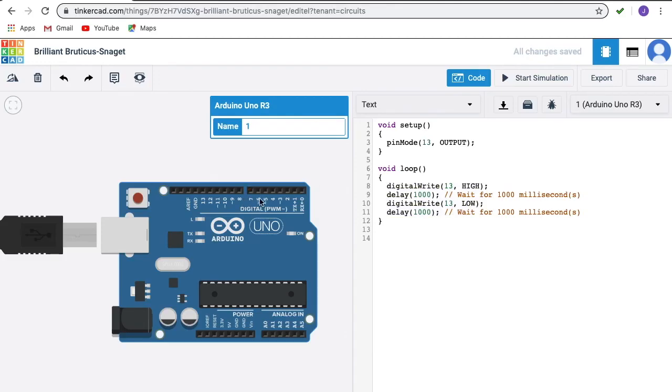This is a digital pin, either 0 or 1 is going to be here in these IO ports, digital IO ports. Since we have configured it as output, digital write is the function used for sending data to this IO pin. Again, we have to refer to which pin I am sending to, and next, what value I have to write, that is logic 1 or logic 0. Logic 1 is referred to as high, logic 0 is referred to as low.